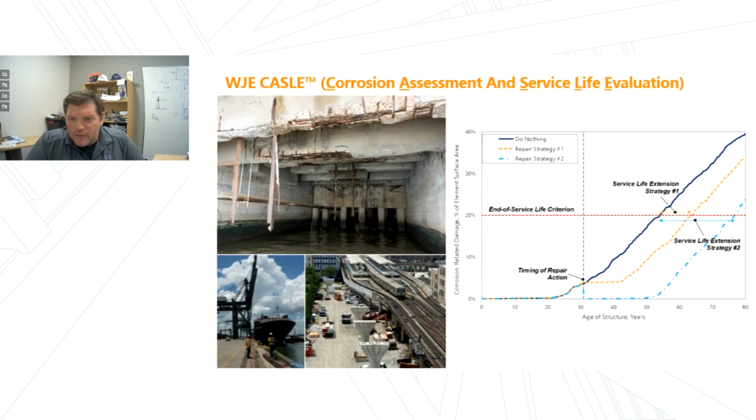Essentially, with service life modeling, we're looking to project damage into the future and then evaluate when our structure might reach its end of life, and then further to evaluate extension strategies, whether that's coatings or sealers to limit future chloride ingress, concrete repairs to address damaged areas, or even corrosion protection methods like galvanic or impressed current cathodic protection. So ultimately, chloride testing is a small portion of a much broader area of practice within forensic engineering.